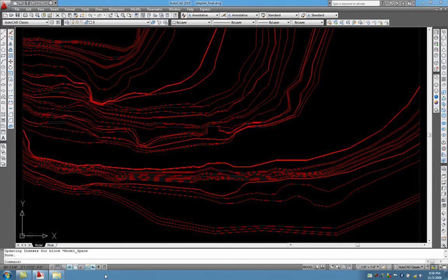And in this video we're going to discuss how to make terrain models from GIS information you're going to receive from cities, municipalities, wherever you get them from. Here is a map that some of the students in the second year are using right now. We are going to go over how to loft these polylines together to create solids that you can then take into 3ds Max and use its soft select tool and its looping tool to select vertices and manipulate the terrain to make it fit your project, or what you're building, your intervention, whatever it is.